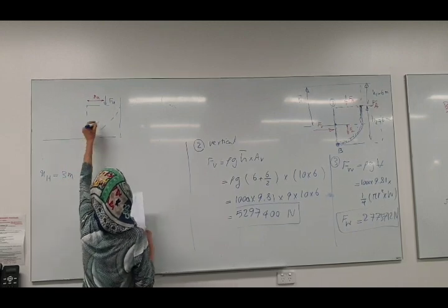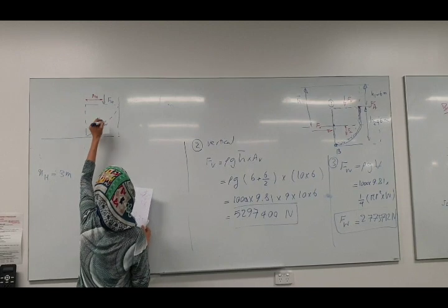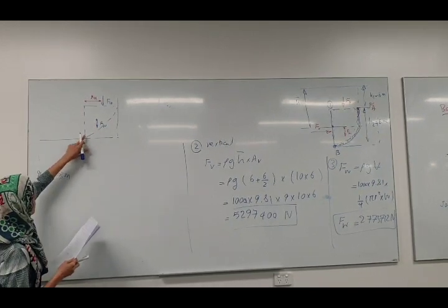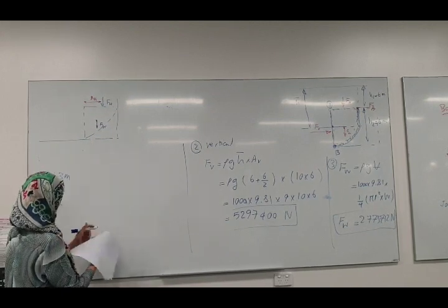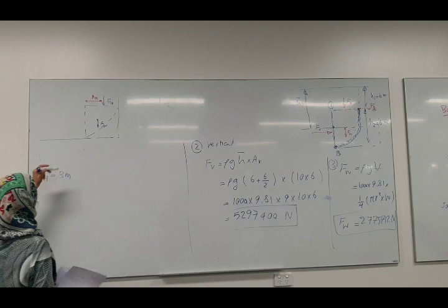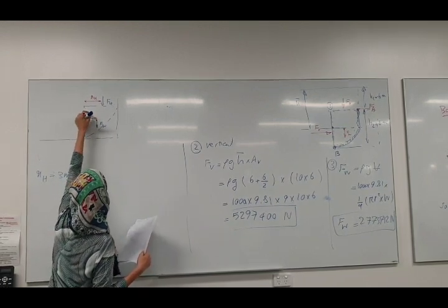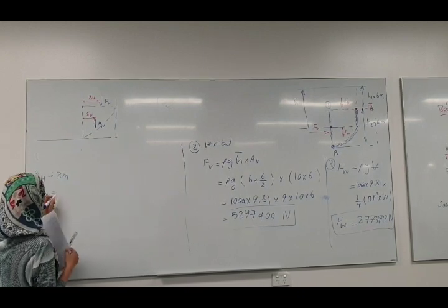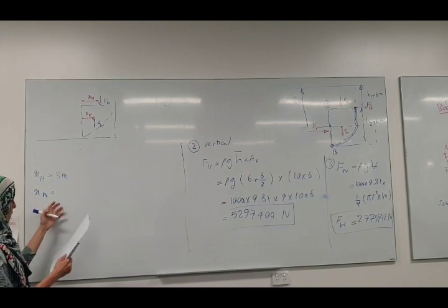The second force is the weight, and we know the weight is acting at the centroid of this shape, which is a quarter of a cylinder. We call this one xw, and for xw you need to look at the slides provided in the lecture notes or textbook.